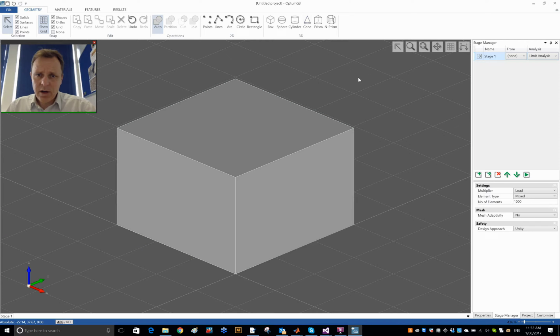For modeling that foundation, I can use either a cylinder, that's somehow the obvious choice, or a so-called n-prism, which is in many ways somewhat more reliable because you can control manually the number of subdivisions in the cylinder. So it's a discrete cylinder with a user-defined number of subdivisions. So I'll select that, and n is the number of subdivisions, the number of sides in this discrete cylinder. I will choose 40 here because we only actually need 1/4 of it. So the quarter we have will have 10 sides, which approximates a quarter circle fairly well.